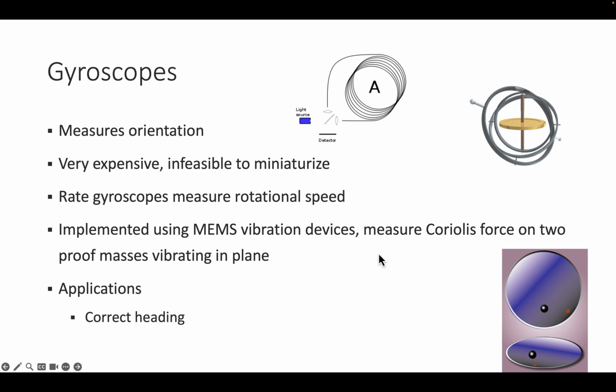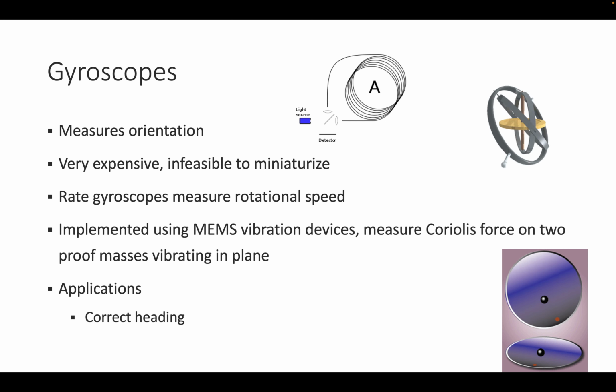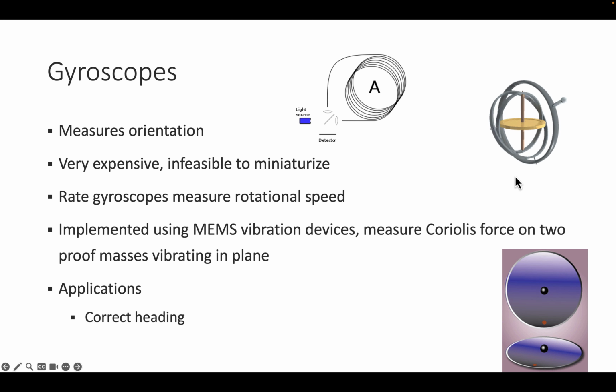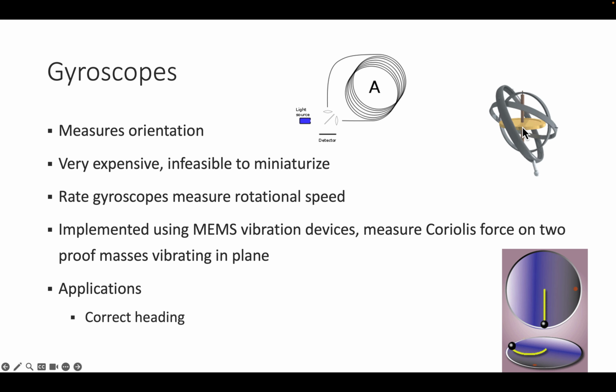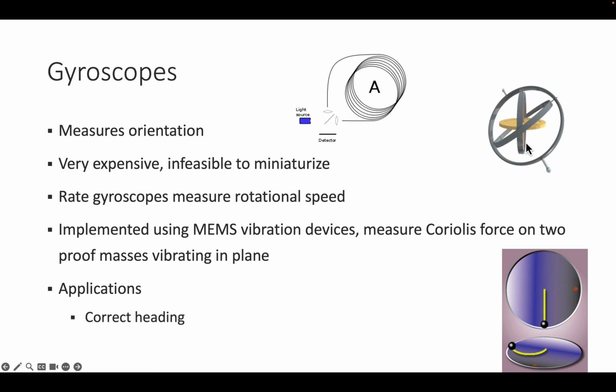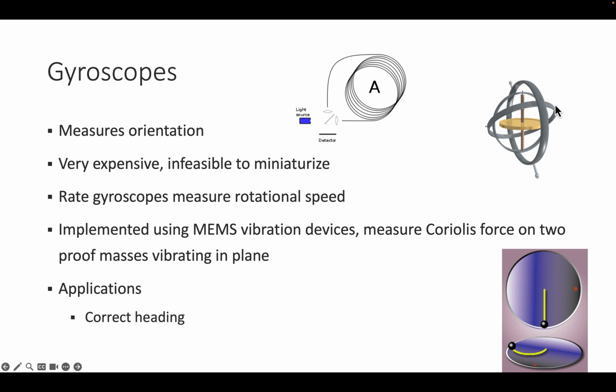Another class of sensors that are very prominent in smartphones are rate gyroscopes. And I say rate gyroscopes because they measure speed, while gyroscopes themselves measure pose. And it might be easier to first understand the gyroscope. You all know this mechanism here. When you spin a top up like that, you can move the outer rings independently of the inside, while the inside keeps spinning and keeps itself in place using rotational inertia.